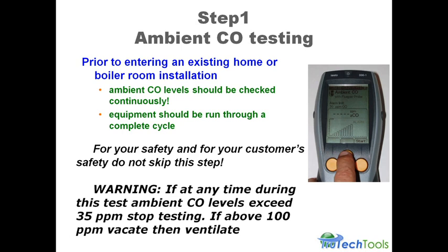And the reason we're going to, even though you got the personal CO meter strapped to your belt or your pocket, we're going to test this because the analyzer is going to allow us to record it. So if we have the ability to print it, which I hope you guys, if you don't own a printer, that you consider purchasing one, because the printer is a very nice way to leave documentation of what you tested on the job. You print a copy for you, print a copy for your customer, staple it to your work order. It gives you the date, the time, the serial number of the analyzer, and you're going to leave a combustion test along with the ambient CO readings that you read, so you can show that while you were doing your testing, while you were there, it was safe.